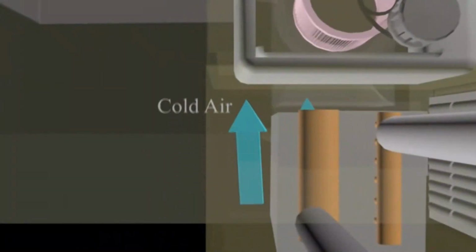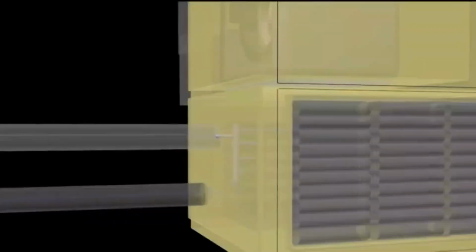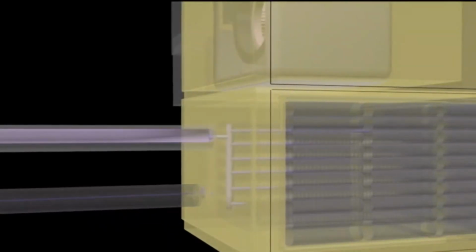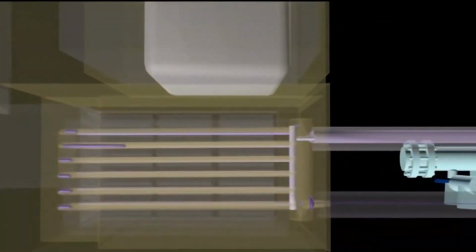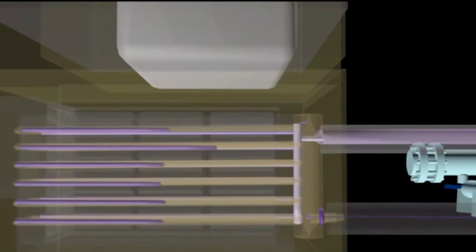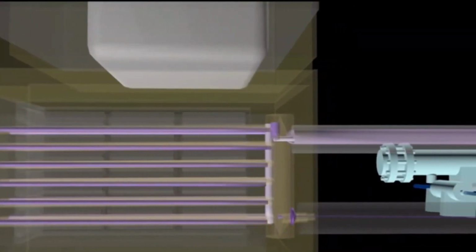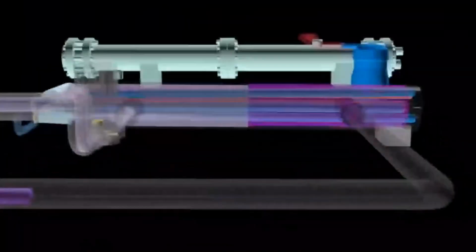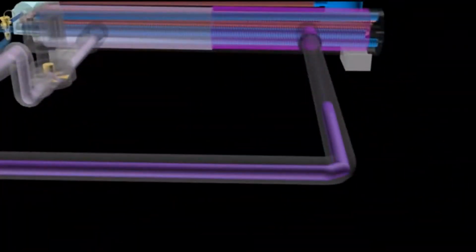Cooling coils commonly used in this system are tube and fin. After absorbing heat from the hot air, the chilled water will be known as chilled water return. Normally the chilled water return pipe will be colored with light blue. Chilled water return will return back to the chiller to transfer the heat absorbed to the refrigerant in the evaporator.